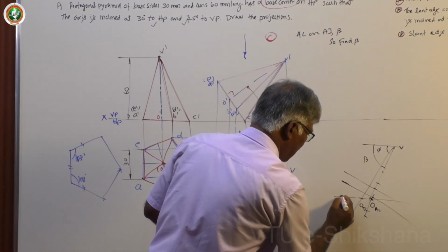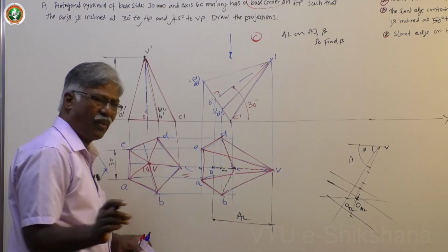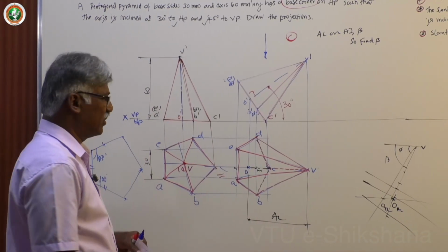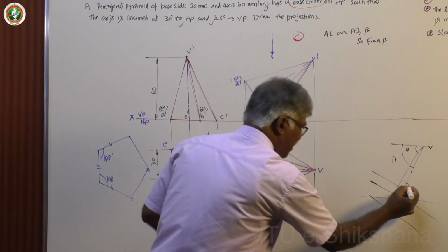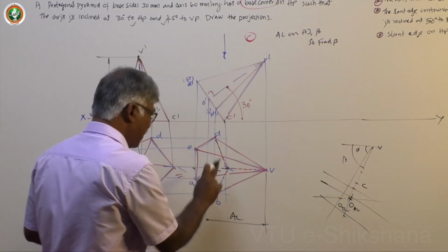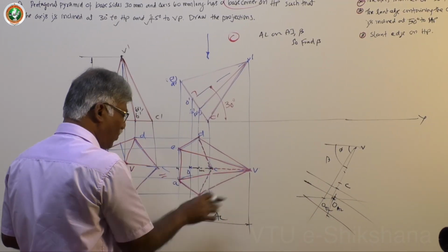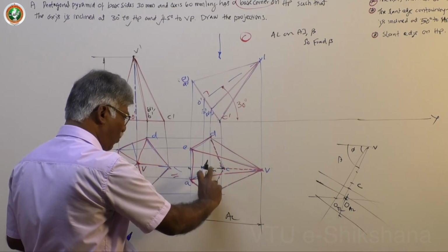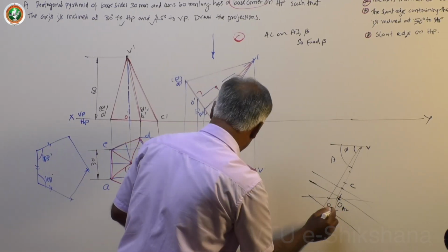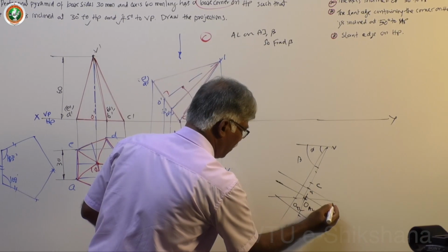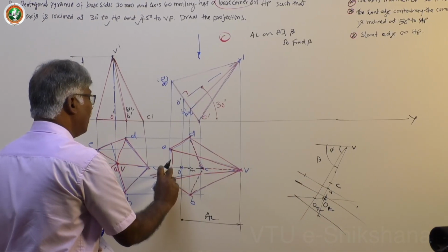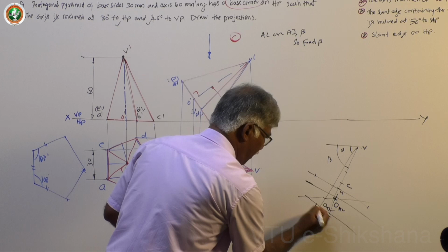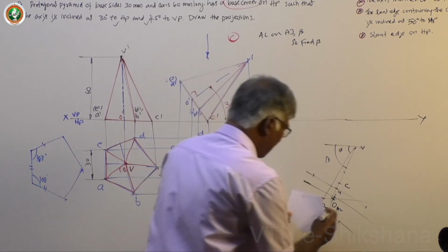Then through that you draw perpendicular lines using a small protractor or any set squares. You are supposed to take only two distances and mark all the points. Let me take MD equal to MB, you mark from this O, not from M. So MD, MB, then you take EN equal to NA, that is all. So you will be getting these points.